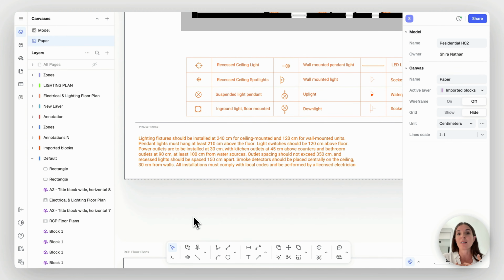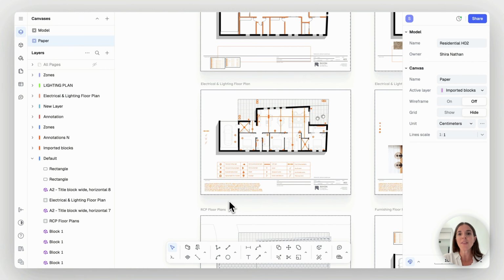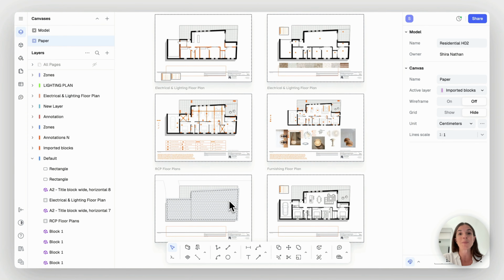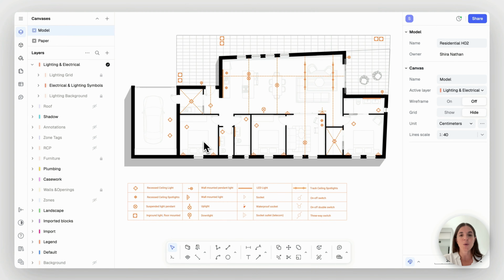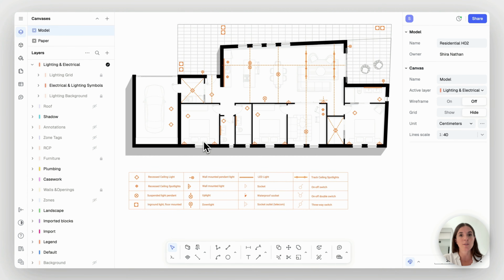So the go-to height for switches, the different dimensions you'd need between sockets and, for example, water sources, something that's really important for kitchens and bathrooms. I have all this information written down, and this is the baseline that construction people working on the project will go according to. Then when I'm back to my model and I want to start adding information, I don't have to overpopulate it with information, and I can only refer to things that are outside of my base rules. So we'll talk about it more as we go. And let's start right now by adding dimensions to our floor plan.